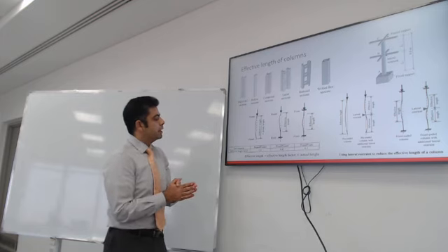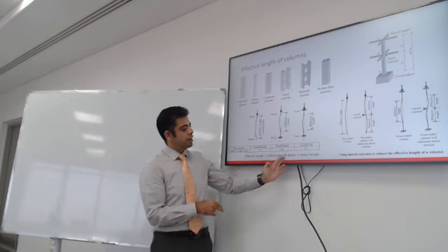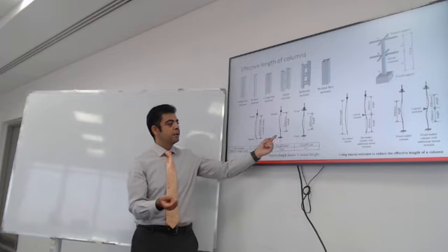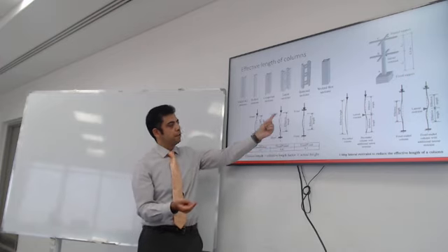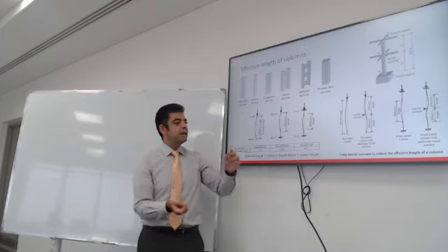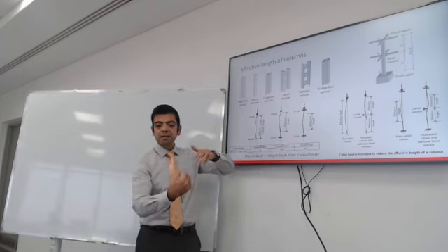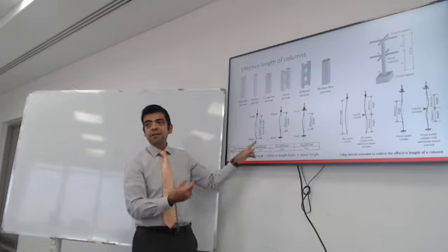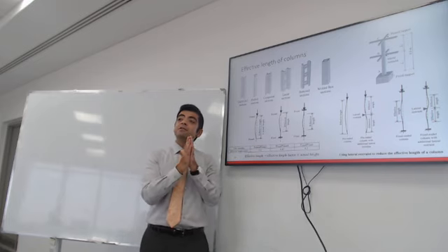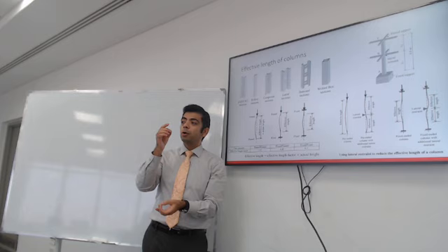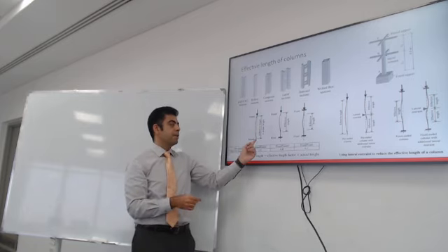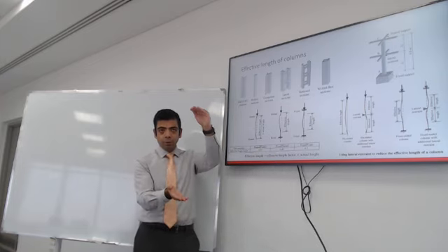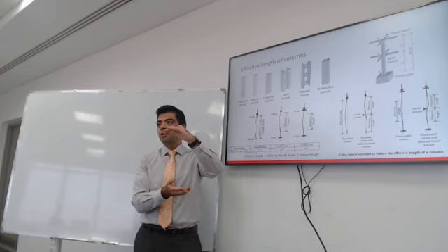The effective length depends on something called the effective length factor. The effective length factor takes into account the types of support, whether the support is fixed or pinned. The reason is that if the support is fixed, the deformed shape is different from a support that is pinned. The most typical, simplest axially loaded column is pinned at the top and pinned at the bottom. In this case, the effective length factor is 1. So its actual length is the effective length. You can always start there.